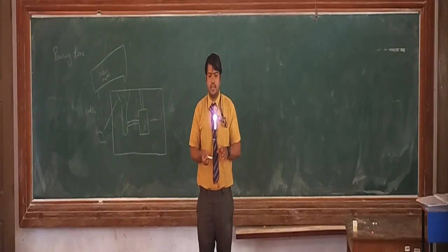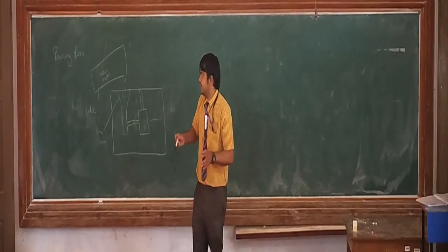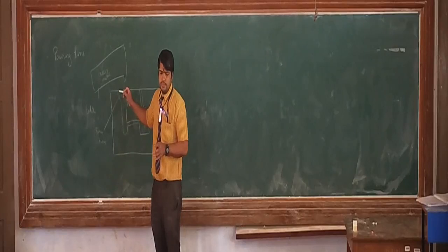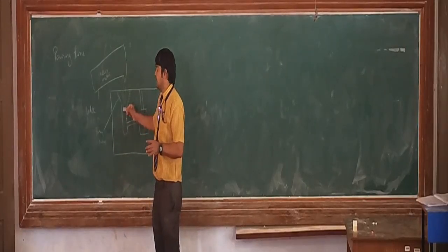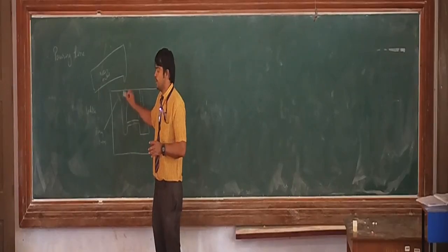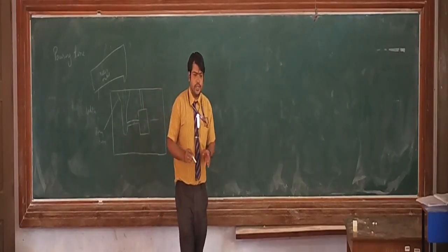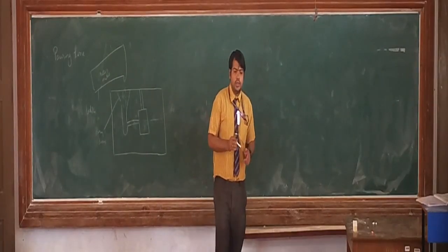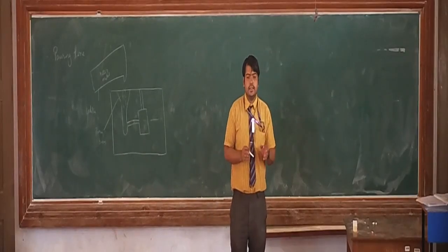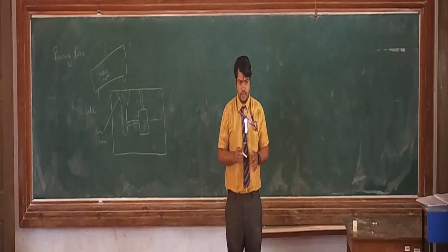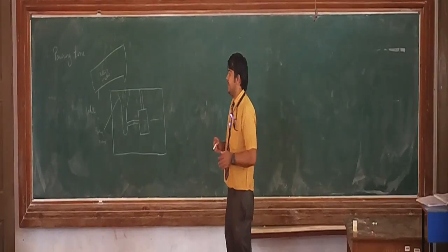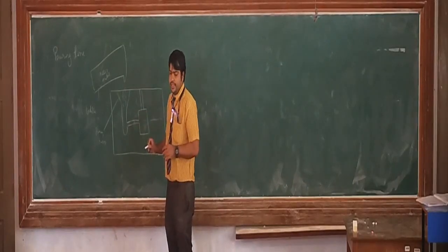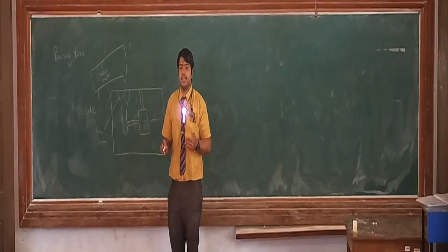Because there are certain drawbacks, if in between it freezes or solidifies once it loses its temperature below the melting point, then the flow of the metal will not take place, it is going to restrict the movement, and it is going to cause defects. For that reason, we pour the molten metal with the temperature on the higher side. So that is done, and here the time required to pour, for example, to pour this particular cavity, how much time is required, that is calculated.